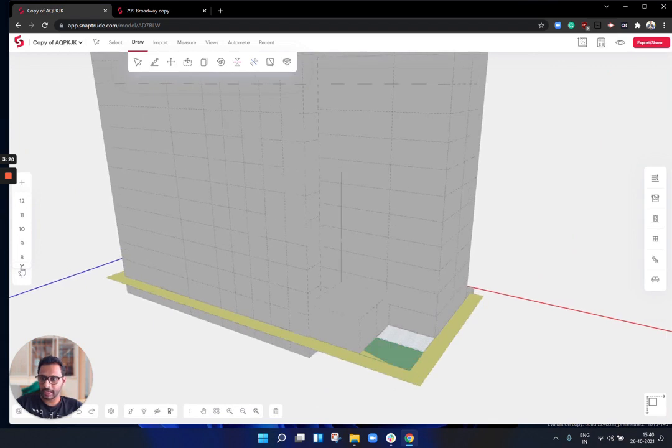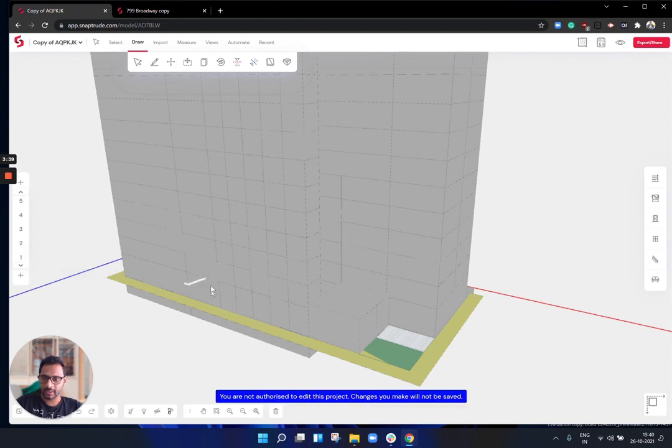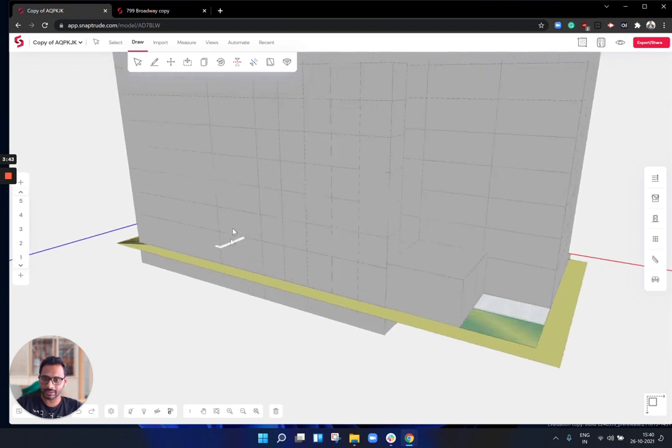The floor to floor height which we were working with by default is about 3 meters, but it can be adjusted, and it's very parametric. Say the ground floor or the first story, instead of the 3 meter or 3000 mm floor to floor height, if you want to make it 4 meters, I'll just click it, and as you saw, it adjusted such that all the other floors moved upwards.